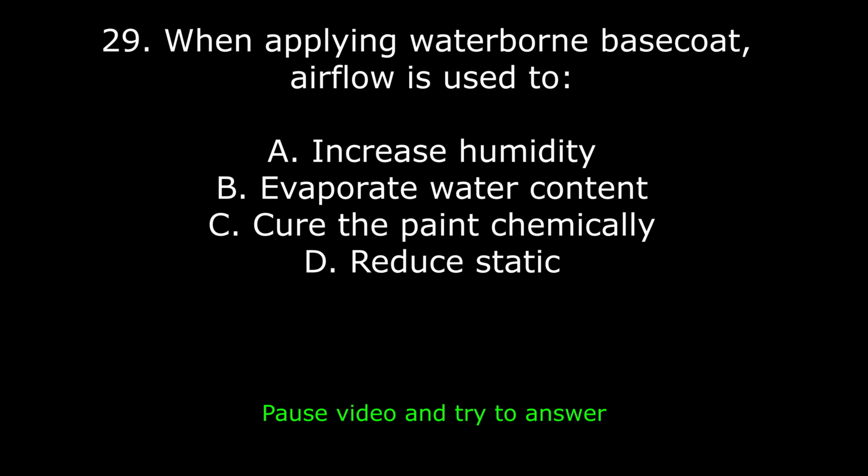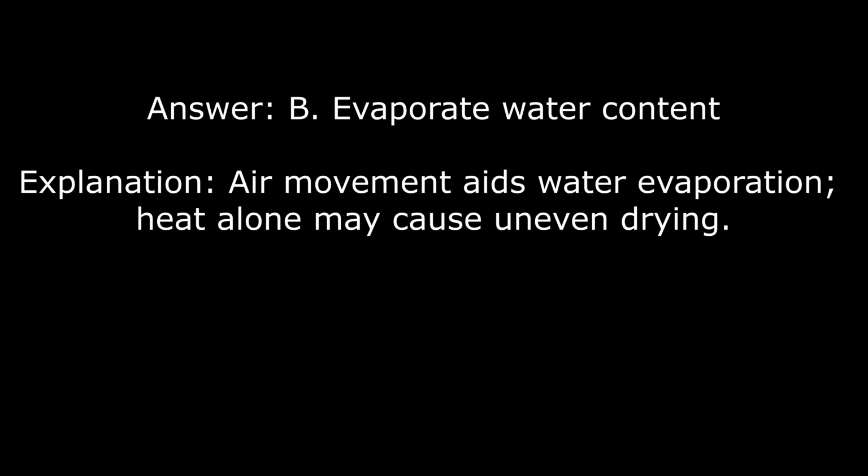29. When applying waterborne base coat, airflow is used to A. Increase humidity, B. Evaporate water content, C. Cure the paint chemically, D. Reduce static. Answer: B. Evaporate water content. Explanation: air movement aids water evaporation. Heat alone may cause uneven drying.